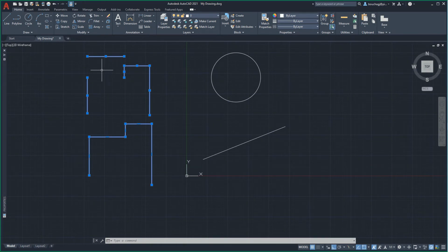Note that even though the line segment moved, the adjacent line segments were unaffected. Left-click on a midpoint of one of the polyline segments. Again, the midpoint will turn red, and the command line will automatically enter the stretch command, prompting the user to choose a point to relocate the polyline segment. Left-click to place the line and exit the command. Note that the adjacent connected polyline segment endpoints stretched and moved along with the relocated polyline segment. Save your drawing.